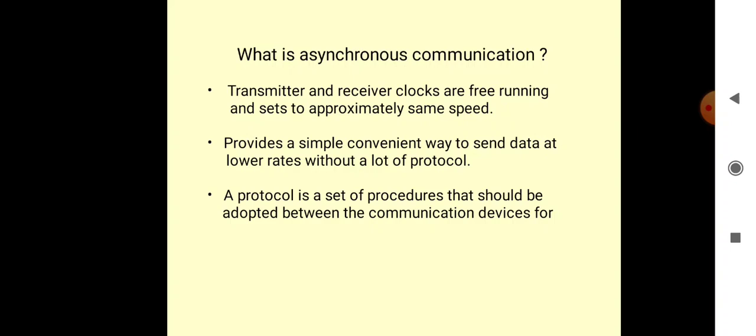How we convert serial to parallel and parallel to serial is by using a device known as UART. UART stands for Universal Asynchronous Receiver Transmitter. This is a digital IC used to perform parallel to serial and serial to parallel data transfer. Most data transfers and operations inside the computer are parallel, but as we know, data communication is mainly serial binary data. UART performs the necessary conversions.